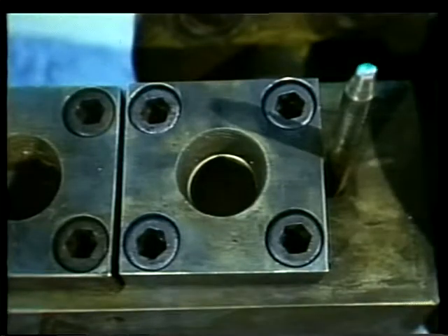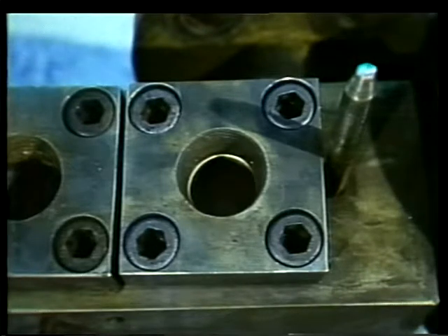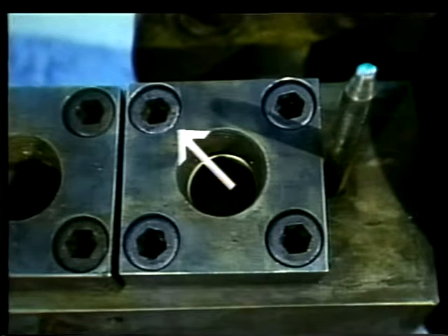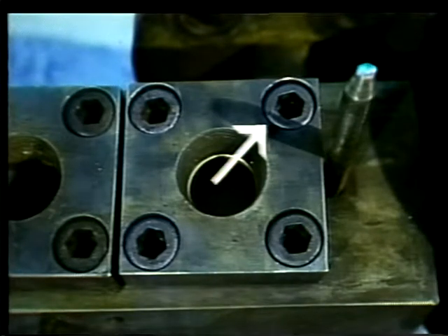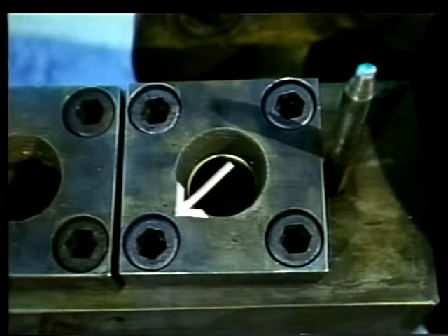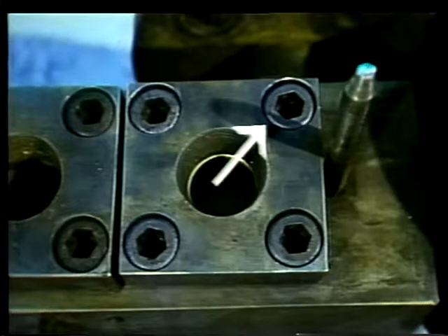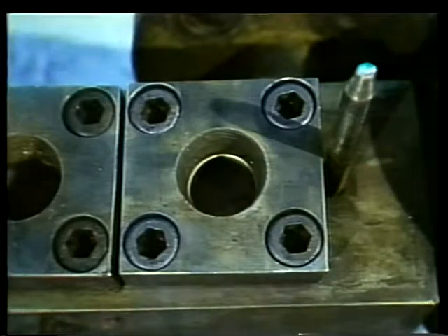Different manufacturers have their own ways of tightening nuts. For this demonstration, we'll tighten the cap screw to your upper left, then the lower right one, then upper right, and lower left. Continue this pattern, increasing the torque in steps until final torque is achieved. When you have rebuilt all the ports, the gauge can be reinstalled and returned to service.